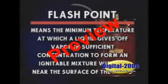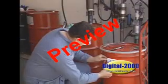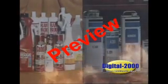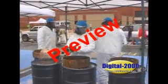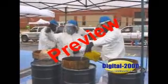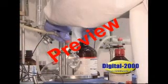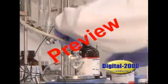Flashpoint means the minimum temperature at which a liquid gives off enough vapor to form an ignitable mixture. In general, the lower the flash point, the greater the hazard. Flammable liquids have flash points below 100 degrees Fahrenheit and are more dangerous than combustible liquids since they may be ignited at room temperature. Combustible liquids have flash points at or above 100 degrees Fahrenheit. Although combustible liquids have higher flash points than flammable liquids, they can pose serious fire and/or explosion hazards when heated.